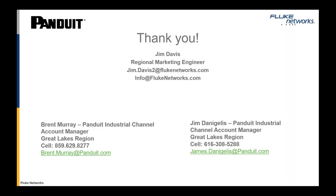But when you start to consider multiple sources of noise, in a commercial setting, we're most concerned about power and data being next to one another, but in the industrial environment, we're concerned about that, but we're also concerned about RF noise and high frequency noise also occurring, right? So the industrial cable may have additional layers of shielding on it, which you've seen, and we covered some of that, or that braided version of shield added to that cable design.